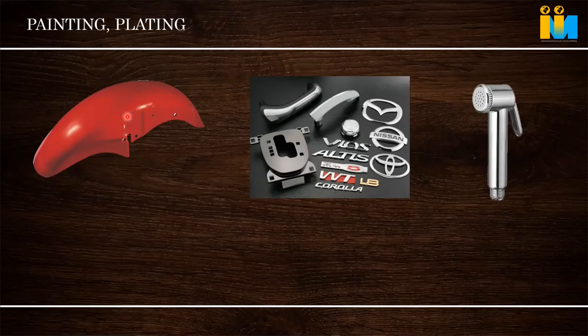Plastic has good mechanical strength, and we have paintability also. Metals are very good for painting because they are conductors, so the paint sticks properly. But plastic is a little bit difficult. But ABS and others can be done. Initially there will be a primer coating, first treatment, then second coating, and then they do the painting, in the whole painting line.